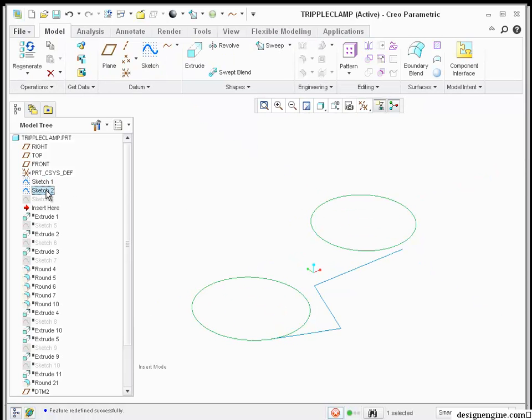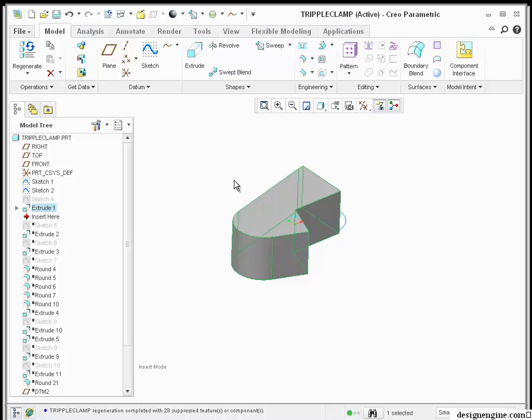Now, this other curve looks at those 2 curves, and the third curve is a culmination of all those geometries, and then this final feature, this protrusion, looks at that curve just beforehand here to obtain its shape. Now, this should be very easy for me to modify. I could have done this all in one feature, but what I did is I broke it up into 3 or 4 features to help me make those changes in the future.